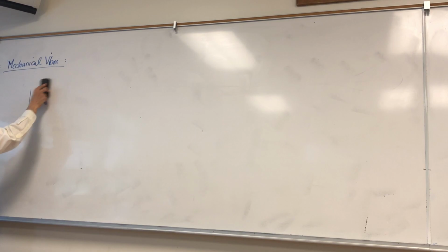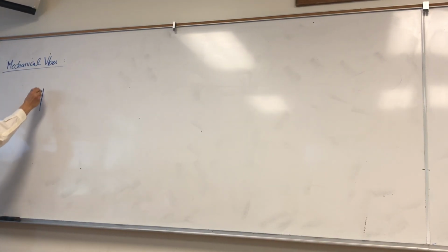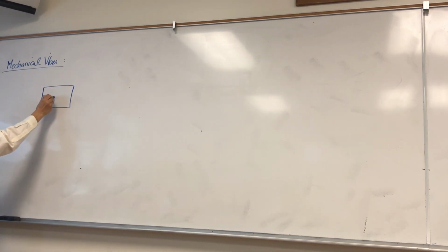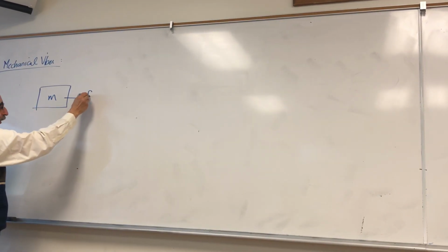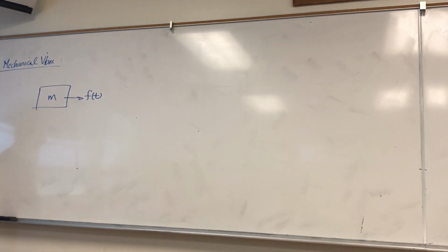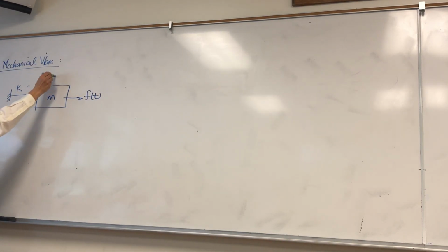So we talked about that, and then we said, okay, if you have a single degree of freedom system, what it means is basically you do have a mass that, when it is acted upon by a disturbance, a time-dependent force, its motion is resisted by an element which we call a stiffness element. Since the motion takes place only in one direction, it's translational, and we're assuming it's linear. Therefore, this is basically a spring, okay?